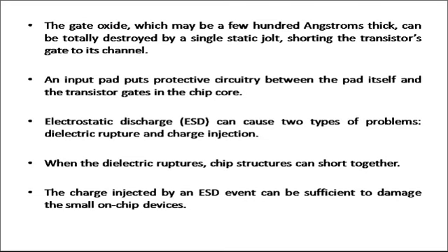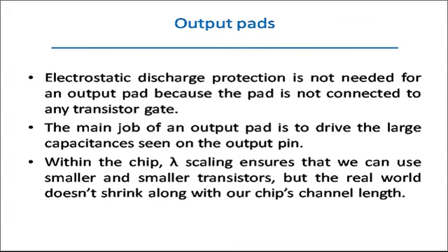An output pad doesn't have to do these things. What is an output pad? The electrostatic discharge protection is not needed for an output pad, because this output pad is not connected to a transistor gate, that is the next transistor gate. The main job of an output pad is to drive the large capacitances seen by the output pin.